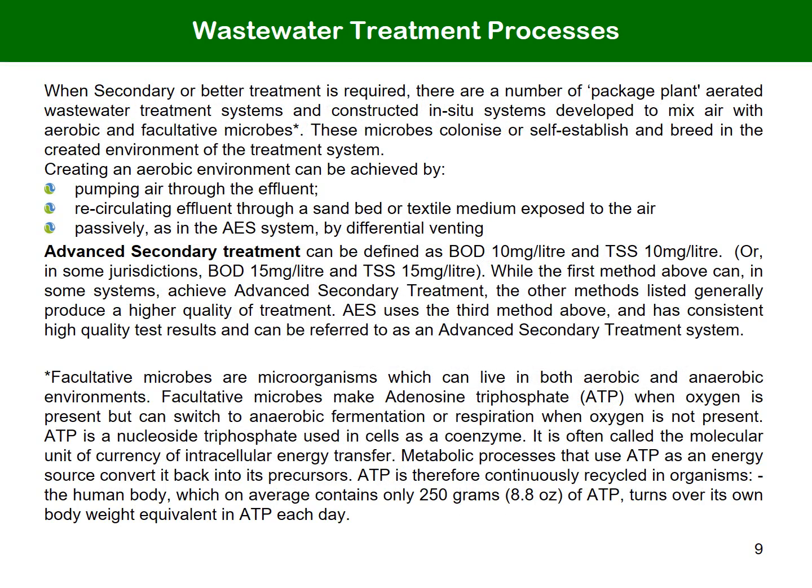Secondary treatment can often be a council requirement due to small area of land available for the disposal field, proximity to surface water, and concern about groundwater contamination. An aerobic environment can be achieved in several ways. Three methods are described on this slide.